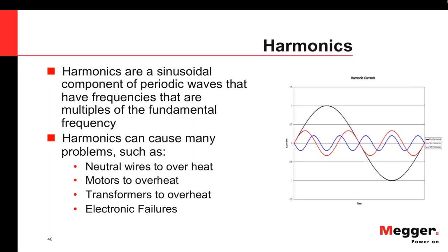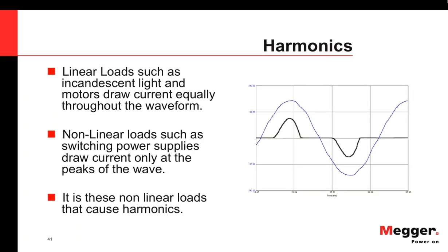And let's first ask, what are harmonics? Harmonics are sinusoidal components of periodic waves that have frequencies that are multiples of the fundamental frequency. They can cause problems such as neutral wires overheating, motors overheating, transformers overheating, and of course electronic failures, as you will see.